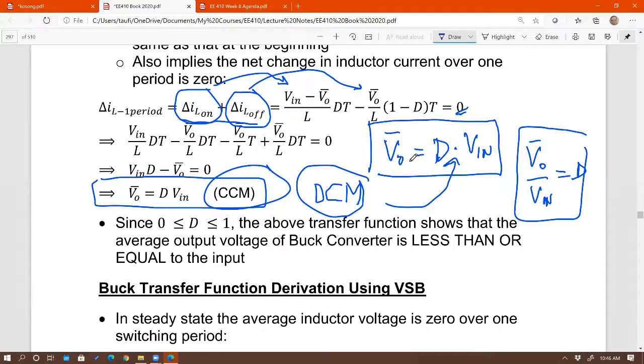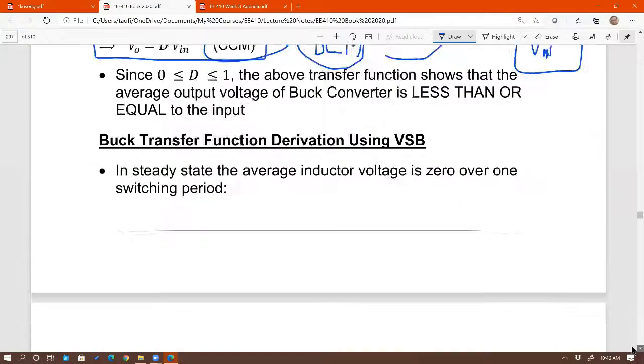So if you operate the converter in DCM, you're going to see I out there, right? Or R, it doesn't matter. R or I out, right? That's more headache, right? You have to deal with current in addition to duty cycle. So here is only duty cycle. So in terms of controller, that's awesome, right? That's a simple controller to make if it's only a function of duty cycle. Make sense, hopefully?